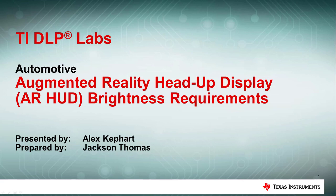In this TI DLP Labs training video, we will discuss the lumen level requirements of augmented reality head-up displays, or AR HUDs. The brightness of an AR HUD is mainly determined by three HUD parameters: field of view, eye box size, and maximum eye box brightness.